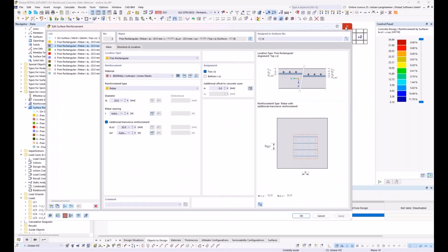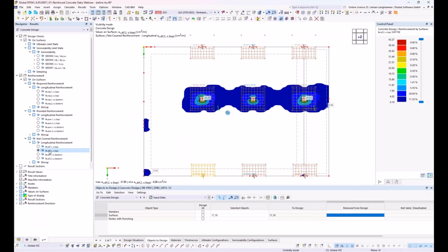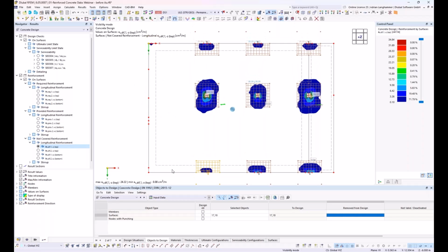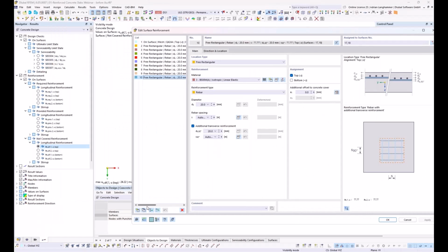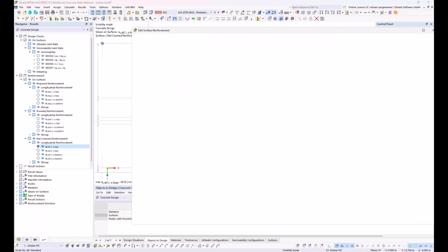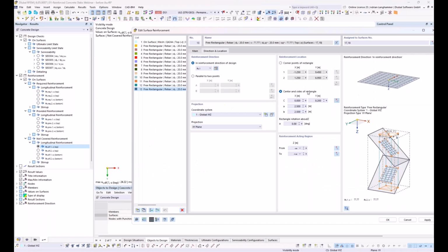I have here in this area also some supports, where there is also some not covered reinforcement in direction 2, and I guess in the upper corner there's also a small area. Here I would also like to use this reinforcement for the support, so I copy it another time for this point and for this point and for this point, and say OK.